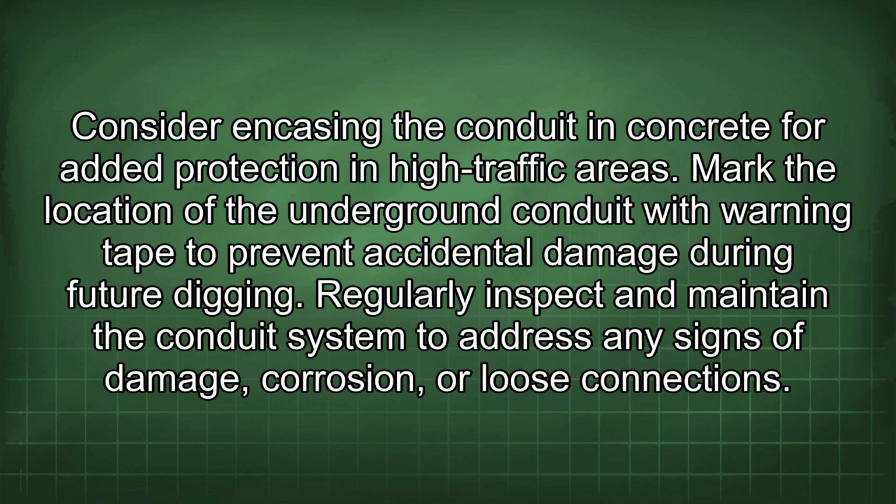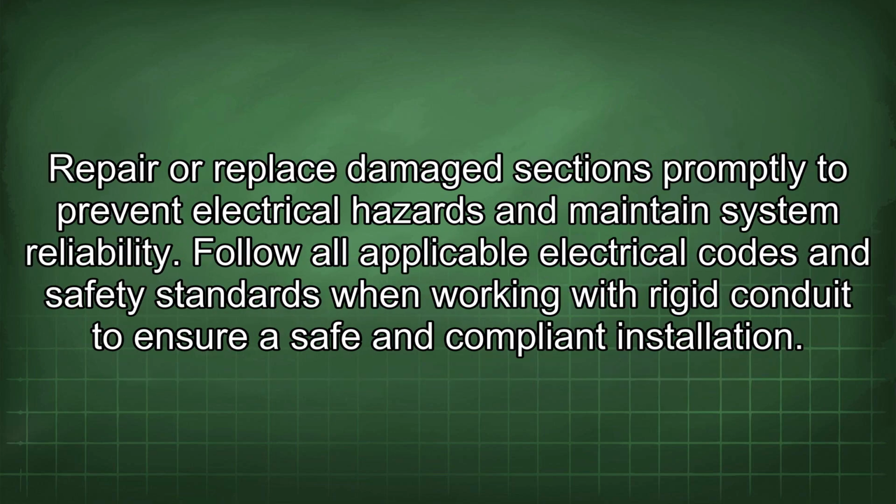Regularly inspect and maintain the conduit system to address any signs of damage, corrosion, or loose connections. Repair or replace damaged sections promptly to prevent electrical hazards and maintain system reliability. Follow all applicable electrical codes and safety standards when working with rigid conduit to ensure a safe and compliant installation.